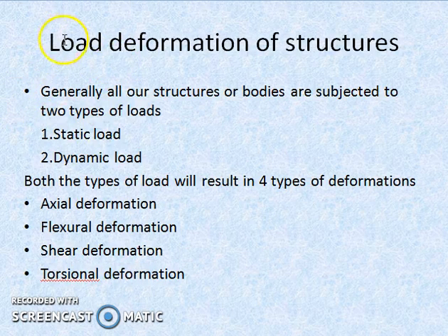Next objective is load deformation of structure. Generally, all our structures or bodies are subjected to two types of loads. One is static, the other one is dynamic. Both types of load will result in four types of deformations: axial deformation, flexural deformation, shear deformation and torsional deformation. These four deformations are due to application of either of those two loads.